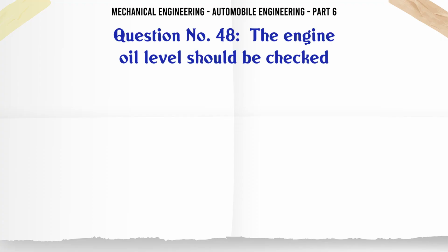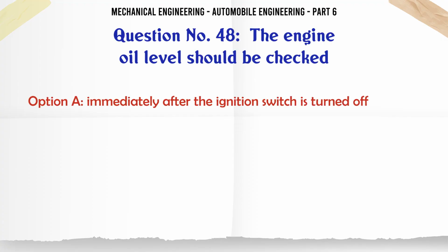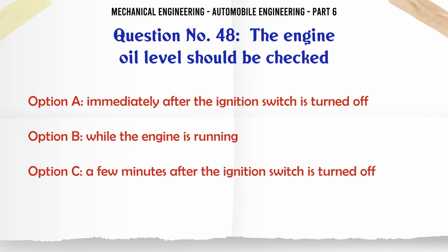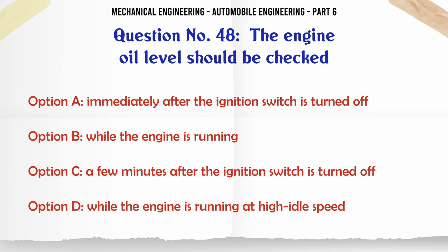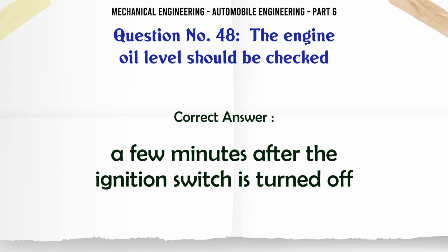The engine oil level should be checked: A. immediately after the ignition switch is turned off, B. while the engine is running, C. a few minutes after the ignition switch is turned off, D. while the engine is running at high idle speed. The correct answer is a few minutes after the ignition switch is turned off.